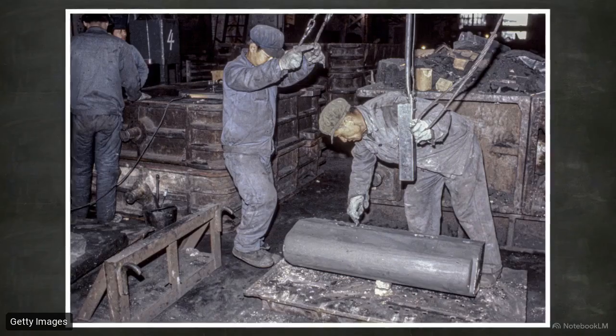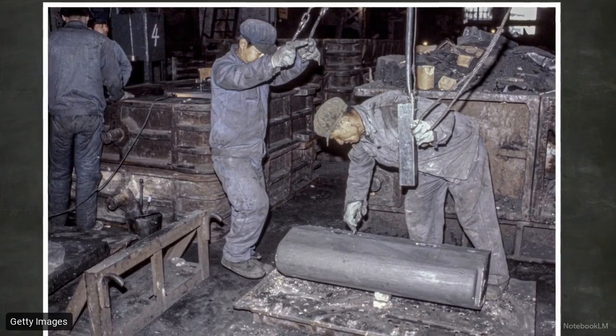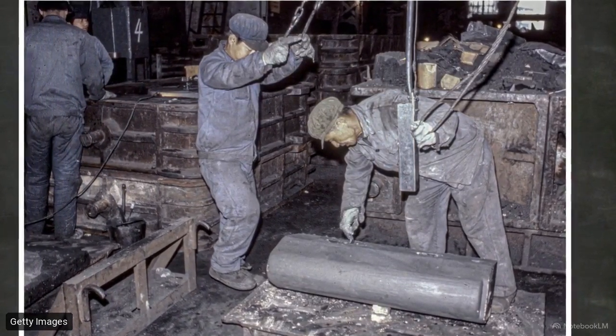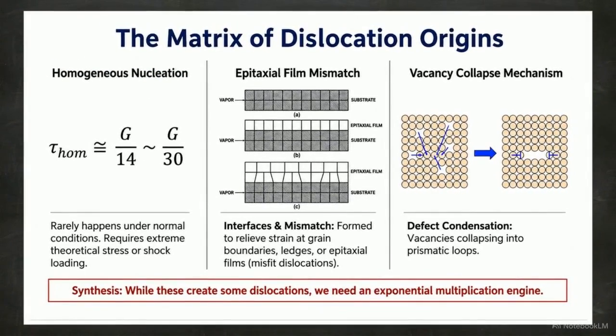This creates a physical paradox. A standard metal straight from casting simply does not possess hundreds of millions of active dislocations. Spontaneous generation, like homogeneous nucleation, requires stress levels near absolute bond strength, never reached during standard loading. Other mechanisms like epitaxial mismatch or collapsing atomic vacancies do create baseline defects, but only yield a small fixed quantity.